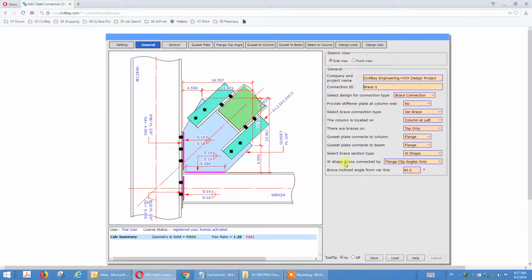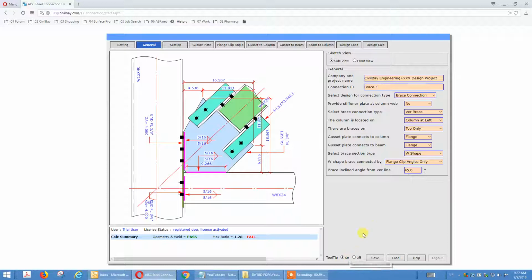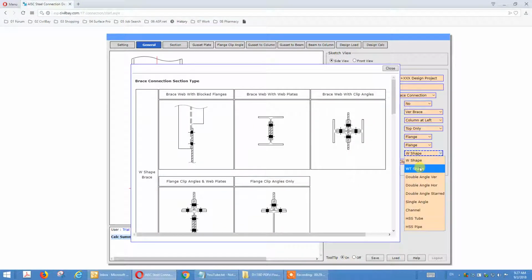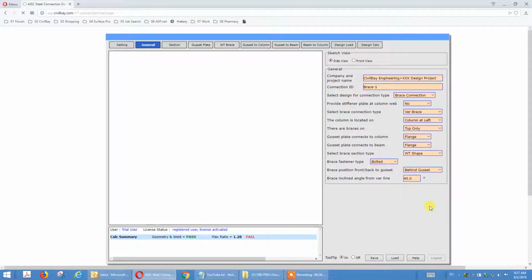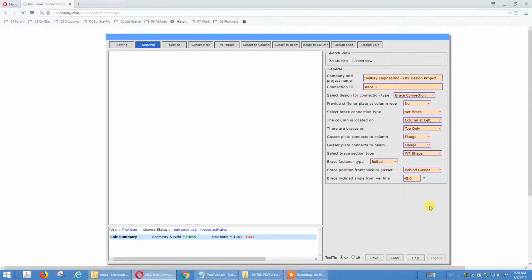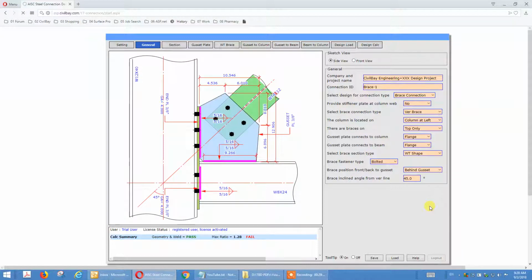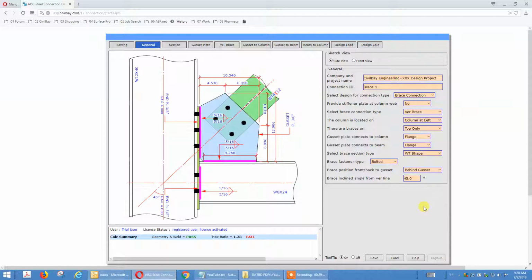Let's conclude our wide flange. So we turn these off, we'll keep this on. Then we go to WT shape. That's only one way of connecting it. That's what you see here, WT flange. We use WT a lot. The problem with that is the eccentric moment. It has a lightweight capacity. Normally for heavyweight brace force, we go to wide flange.